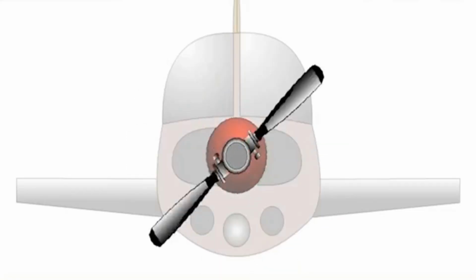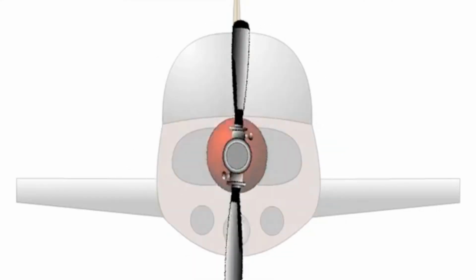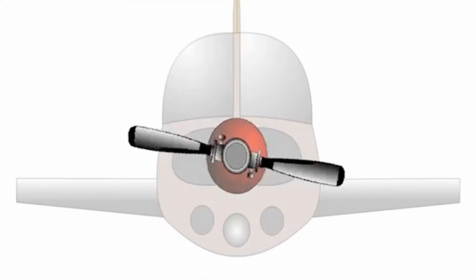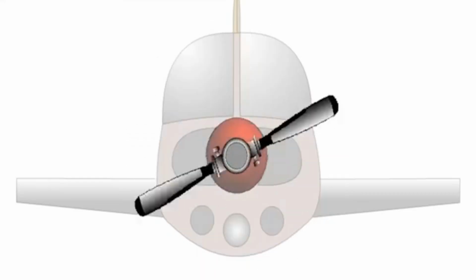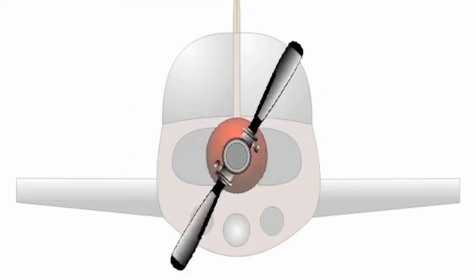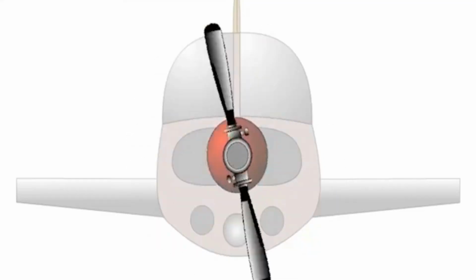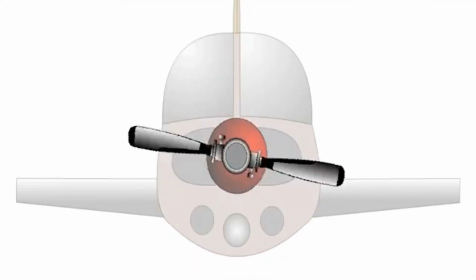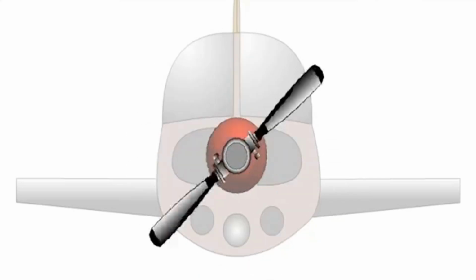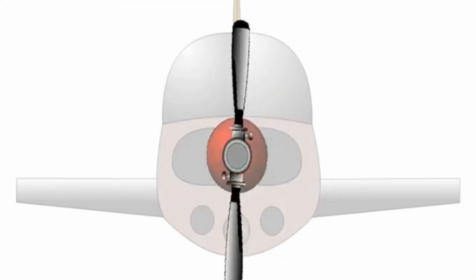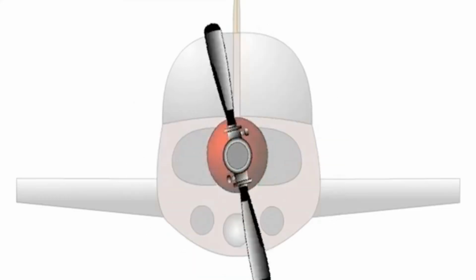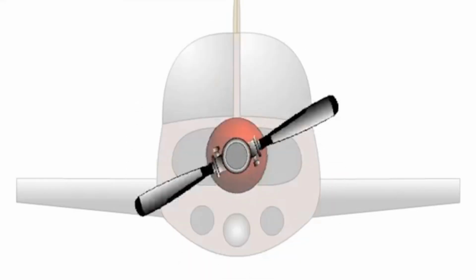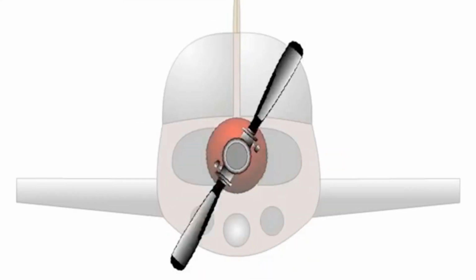A propeller must be able to absorb all the shaft horsepower developed by the engine, and it also must operate with maximum efficiency throughout the required performance envelope of the aircraft. The critical factor here is tip velocity. If tip velocity is too high, the blade tips will approach the local speed of sound, and compressibility effects will decrease thrust and increase rotational drag. Supersonic tip speed will considerably reduce the efficiency of a propeller and greatly increase the noise it generates. This imposes a limit on propeller diameter and RPM, and the true airspeed at which it can be used. Another limitation on propeller diameter is the need to maintain adequate ground clearance.